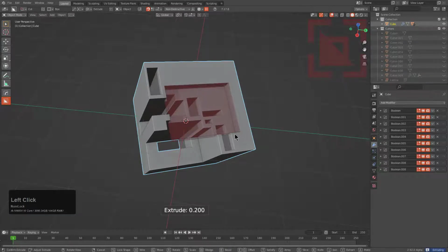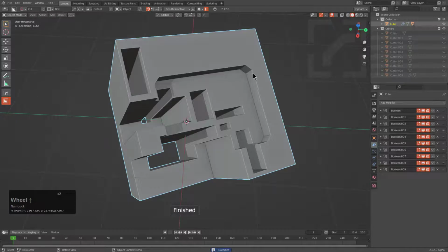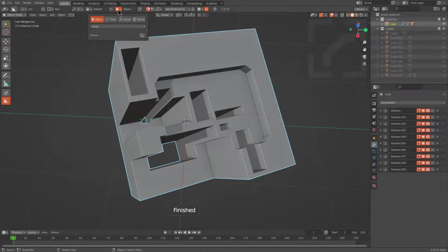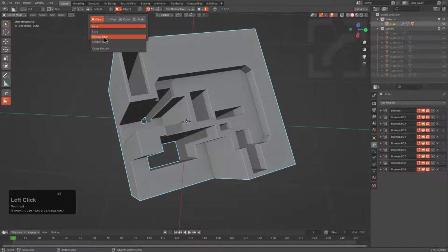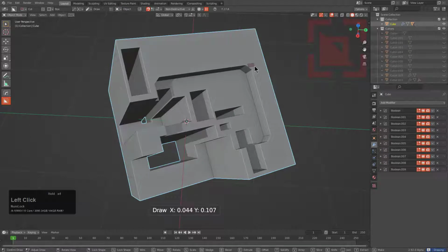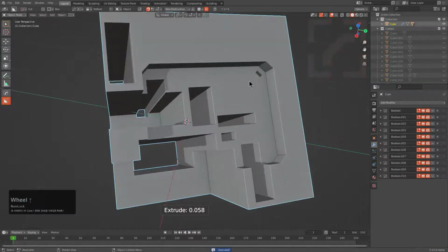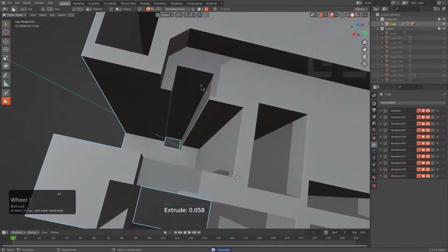However, there's alternative ways that you're able to work inside of BoxCutter. One of those is utilizing the longest edge or the nearest edge. So if we expand on our orientation panel, we can see these options. And we're just going to turn this to nearest edge. And just notice that our orientation did not change, but whenever we draw on the inside, our orientation did change over to the nearest edge that we're looking at in this area.